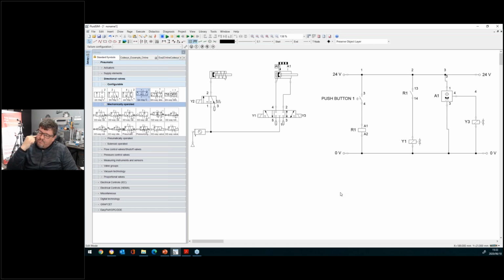That means the moment the power falls away, your machine will reset to home position. For safety purposes, you will use a single solenoid valve spring return. That's the basic answer for that. Any other question? Okay, Don.